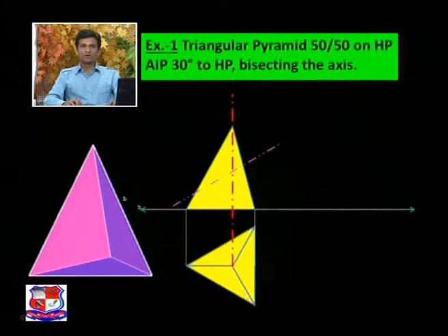If you look from the top, these three triangles can be represented by these slant edges, which meet at this center of gravity or at the axis position. Now from this point, you can see here the point of intersection of this cutting plane and this slant edge. Two slant edges are there, so 2 points are here.